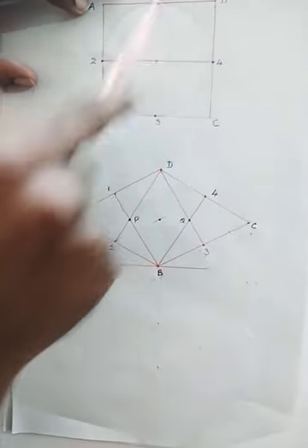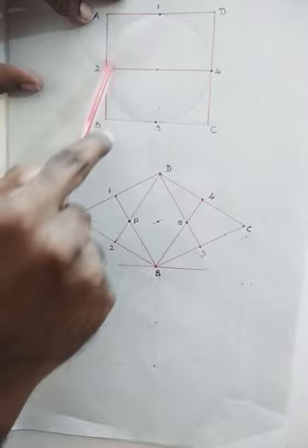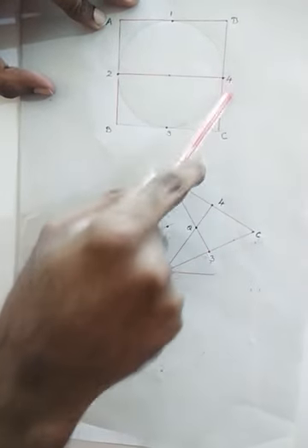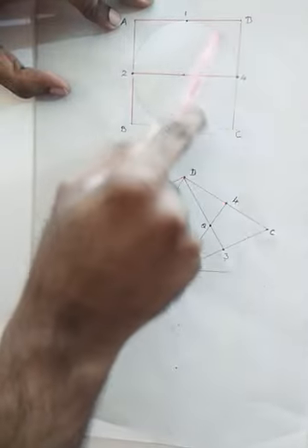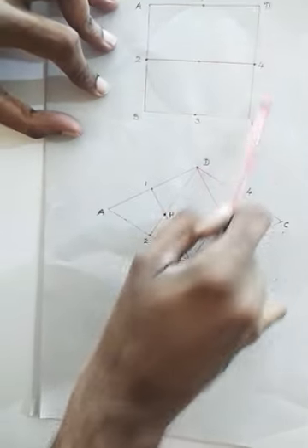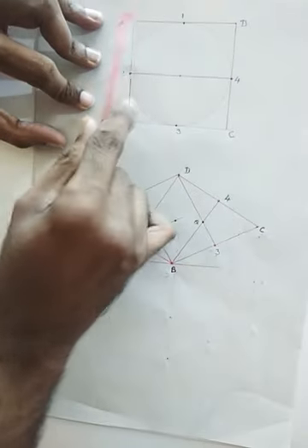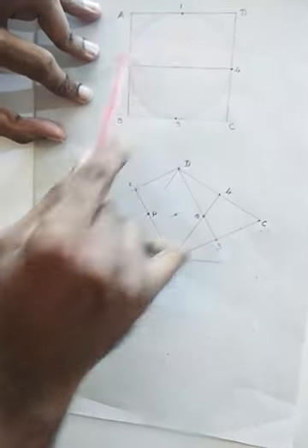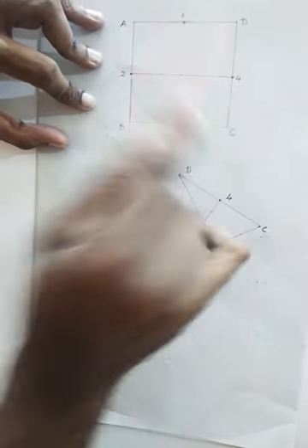I have not drawn the front view, I have just drawn the top view. So first I will be drawing the top view of the cone. It will be a circle. The dimension has to be taken from isoscale. As usual, once you have drawn the circle, you inscribe the circle inside a box. Since it is a circle, we will be getting a perfect square. I am naming the corners as A, B, C and D. You identify the midpoints also. It will be 1, 2, 3 and 4.